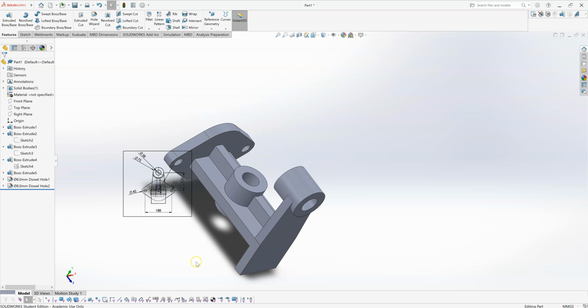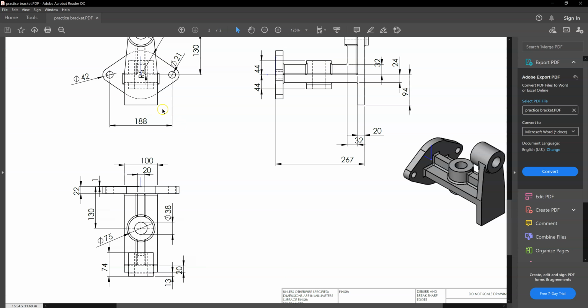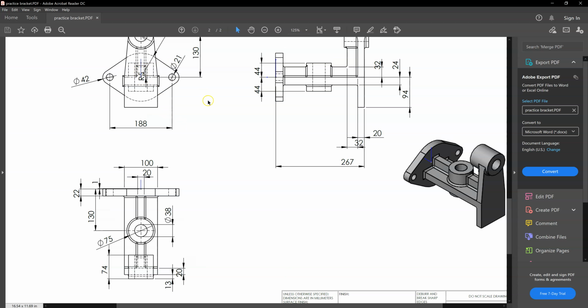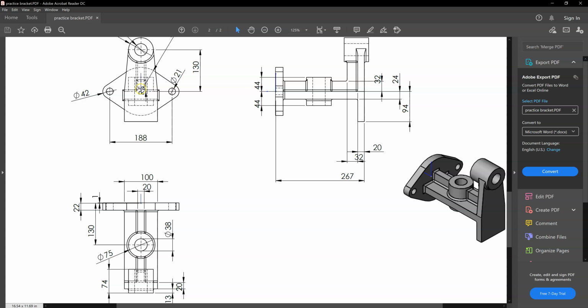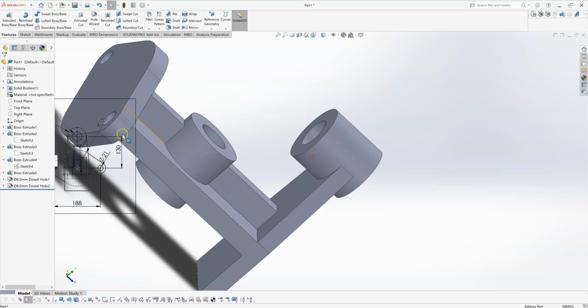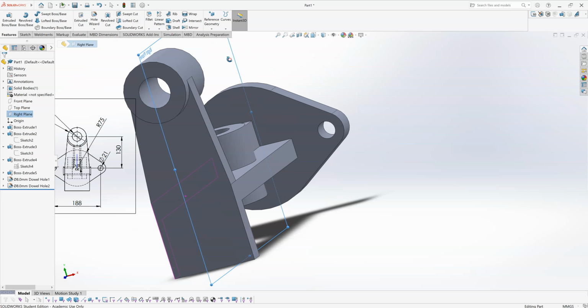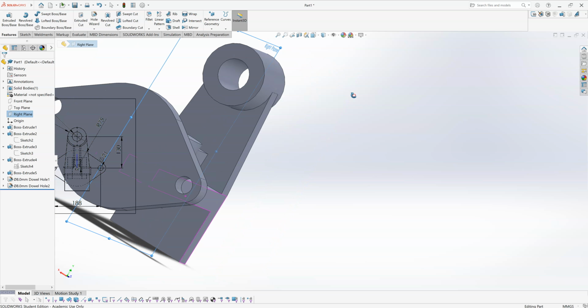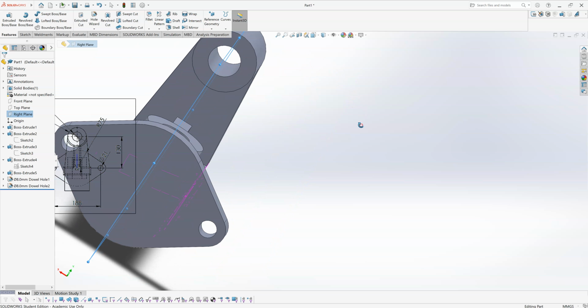So the last thing then is there are some fillets on the part in general. I think they're a radius 5 fillet, radius 5 all throughout. Actually, sorry, one last feature here, which is this web coming from here up to meet the cylindrical face up there. So you could draw it on the right plane here, for example, and extrude it out mid-plane. So extrude it out in 2 directions, like so.